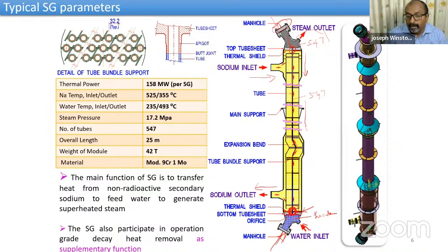So there will be a primary coil and a secondary coil. And when the primary is excited, the phase difference is considered to be the flaw indicators. So there will be a continuous plot between the phase difference between the primary and the secondary, which will give an indication for the inspectors to understand if there is any abnormality along the thickness of the tube. If there is any abnormality in the tube, it can be identified from the remote field eddy current technique.